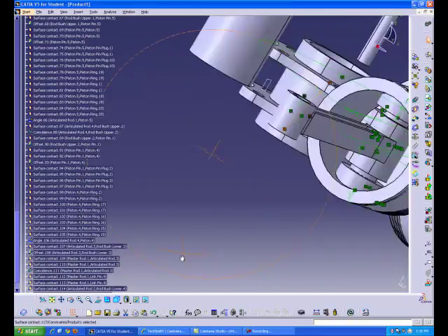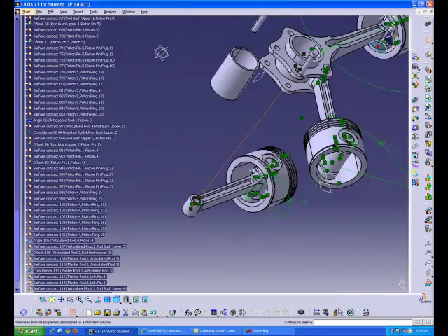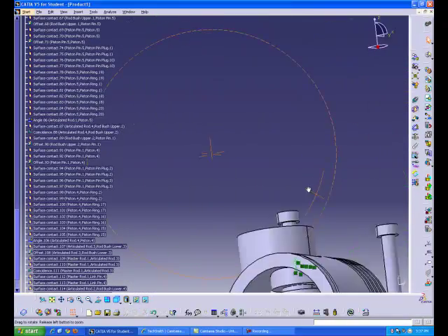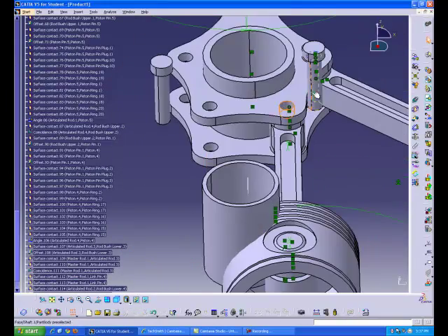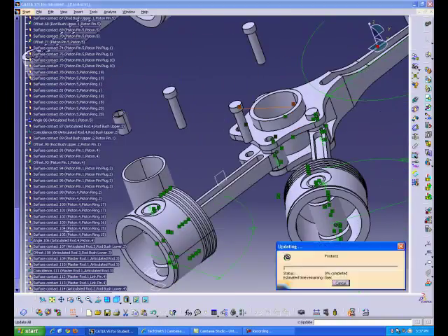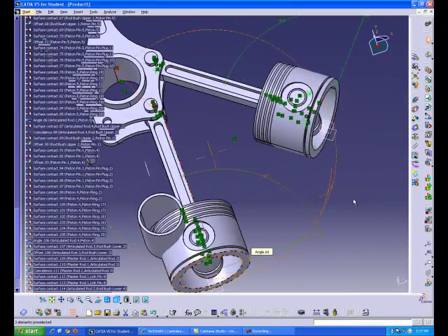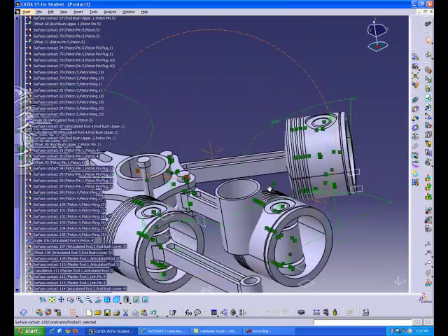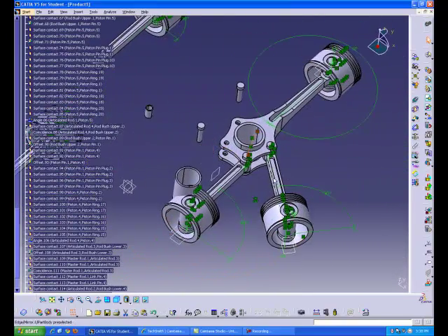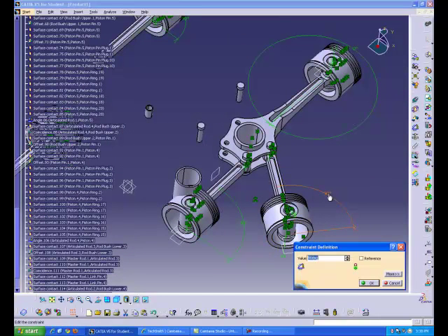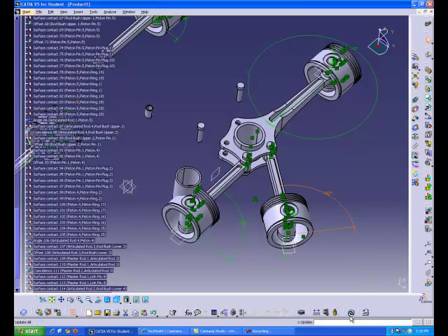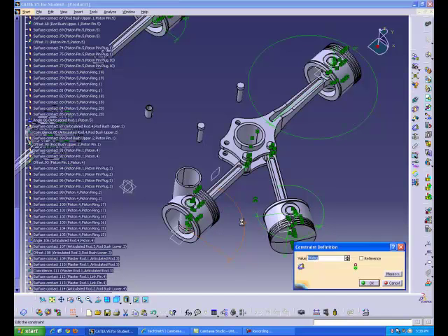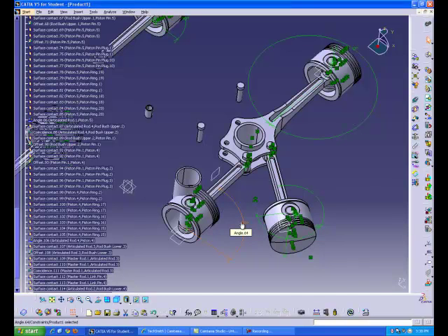But you'll notice when we do this that something changes. When you click update to put the articulated rod in the master rod, the piston head changes directions. In order to change this, all you have to do is rotate the part so you can see it, and then double click on the 90 degrees and change it from 90 to -90. Select OK and click update. And this will turn the piston around so it's facing the proper way.